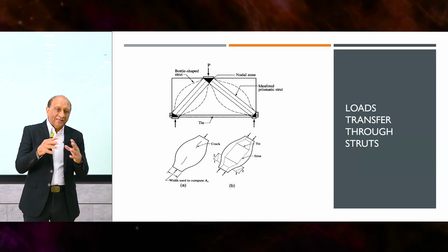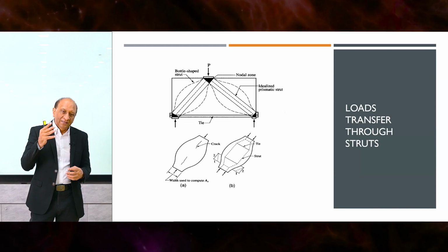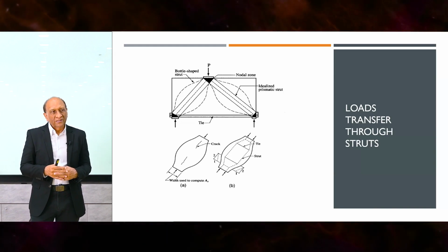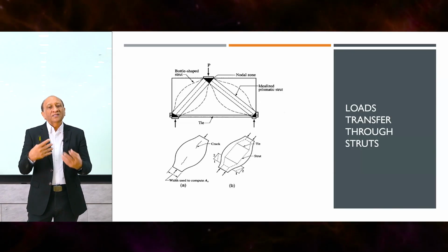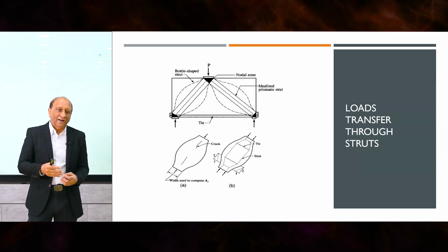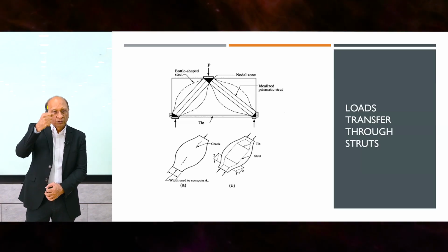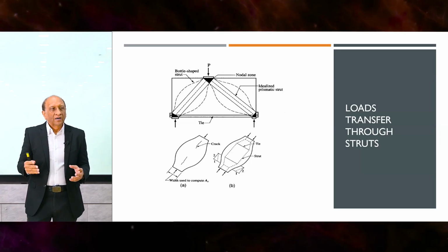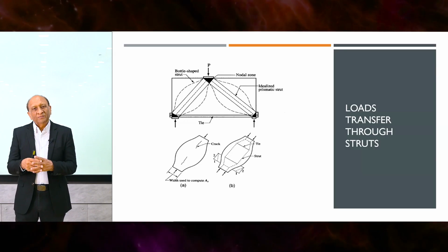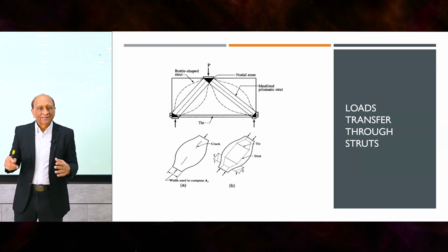And as you can see, when the stress is spread, the angle will change. And when the angle changes, internal substructures will form. Ties and struts will form within a strut to prevent that diagonal crack that you see, which is going to be just like a cylinder. When you test it and apply axial load, it splits sideways because of the Poisson's ratio. The same thing will happen here, and also the stresses are going at an angle.